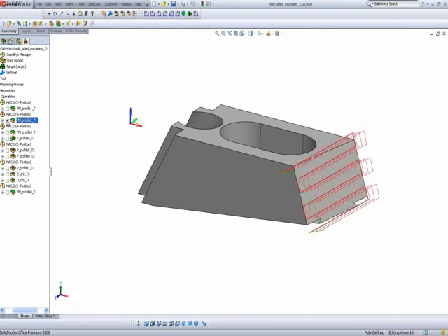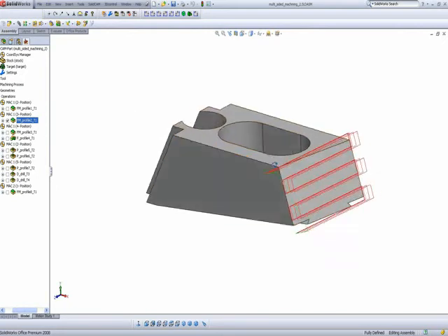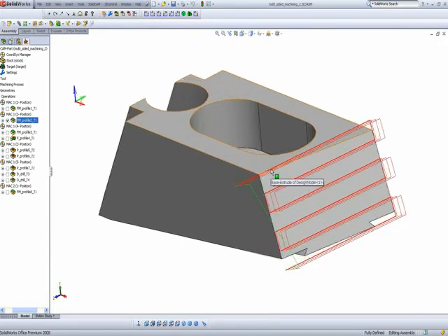So again, as you can see, I've done that. And note that the tool path is going across this way on purpose because, remember, I am holding it apart from the bottom over here, and I don't want to work this way, possibly having a crash into the table itself.